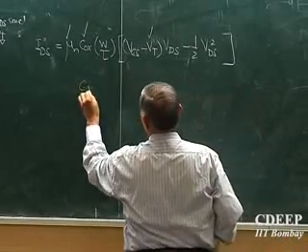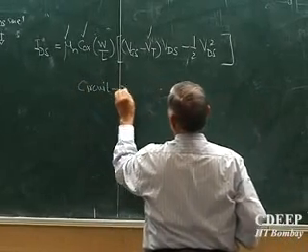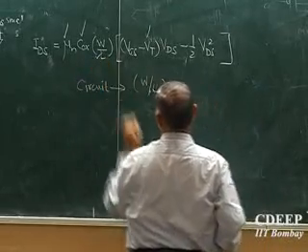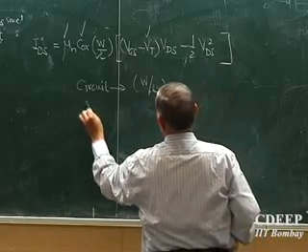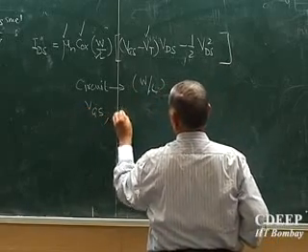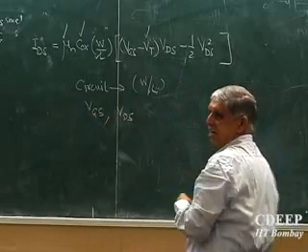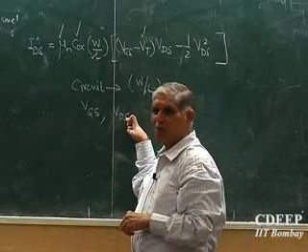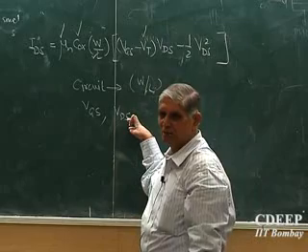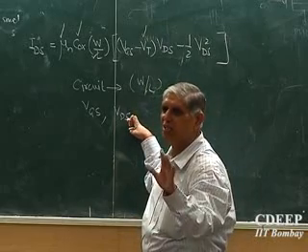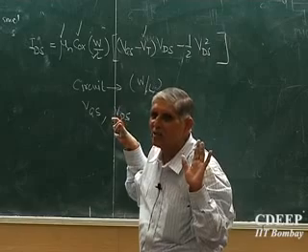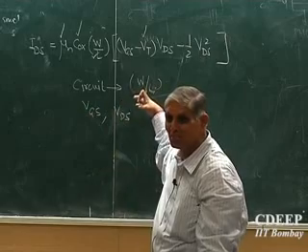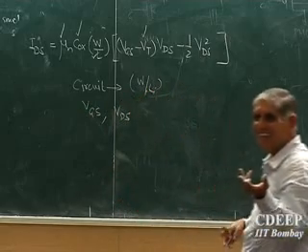For the circuit person, my parameters are W by L, of course, which is fixed by technology actually, but the ratio of this, VGS and VDS, are the only things in my hand. Is that correct? VGS is normally fixed by the technology people itself. They say the maximum power supply given to you for a given technology is 1.1 volt. Finished, maximum volt. So that also went out of my hands. So current can only be obtained from here, from the width. Okay. That's what the designers do.